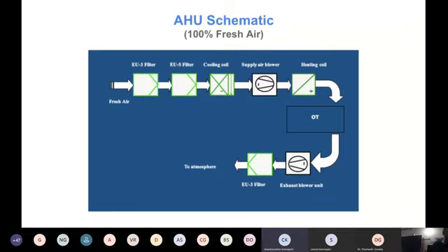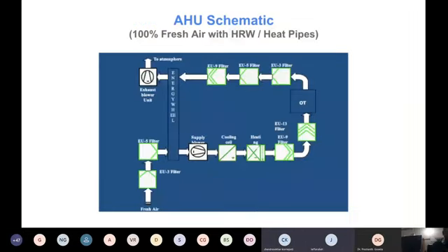Now, when we adopt this kind of system, how do we arrest the recurring loss? Increase in the fresh air. When we select a fresh air system, the normal recirculation system tonnage will be 3 times, as higher temperatures are continuously pumped into the area which has to be cooled. So how do we handle it? With 100% fresh air and 100% exhaust, how do we reduce our recurring cost? How do we not waste our energy, the enthalpy which is pumped in and completely thrown out?